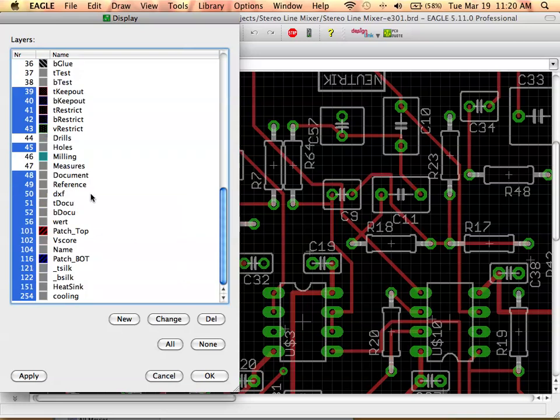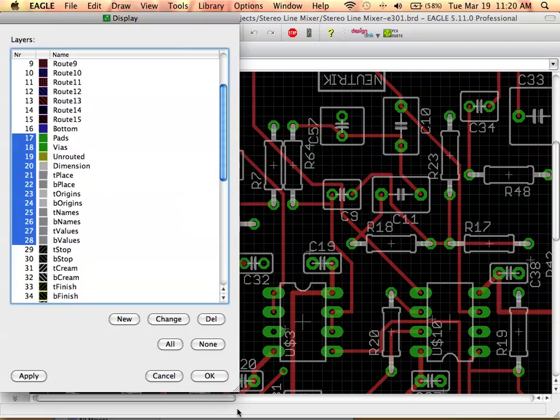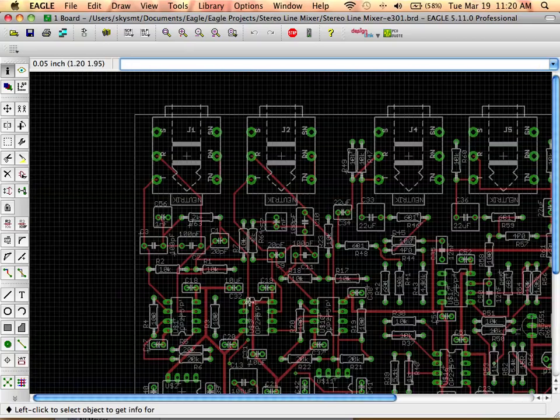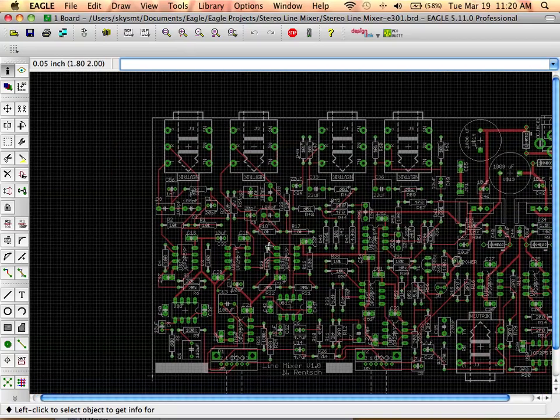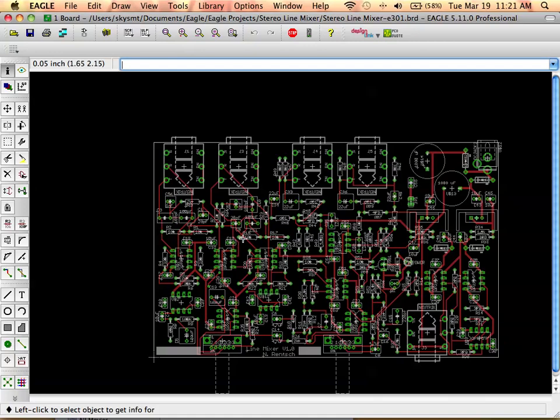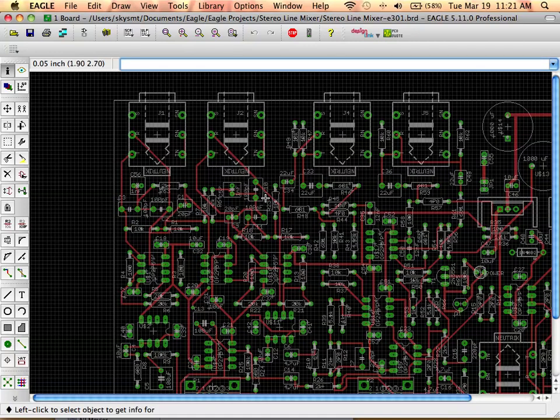That being said, part of what you're graded on and what you should practice is designing an uncluttered layout so that your design is visually organized. Remember, as PCB designers, whether you're designing for yourself to assemble the board or somebody else to do it, you want to implement good placement and good visual clarity and cleanliness so that it's easier for the board person who's going to build the board to make it.